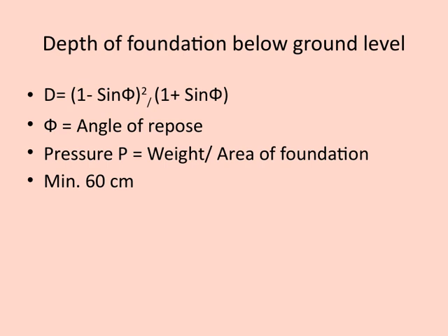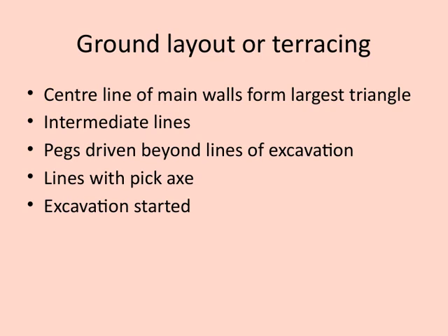Additionally, we recommend a minimum depth of 60 centimeters below ground level. This minimum ensures adequate stability and helps prevent issues like frost heave or surface erosion from affecting the foundation. By understanding and applying these concepts, we can design foundations that are both safe and efficient, supporting the overall integrity of the structure. Let's take a closer look at the ground layout or terracing process.